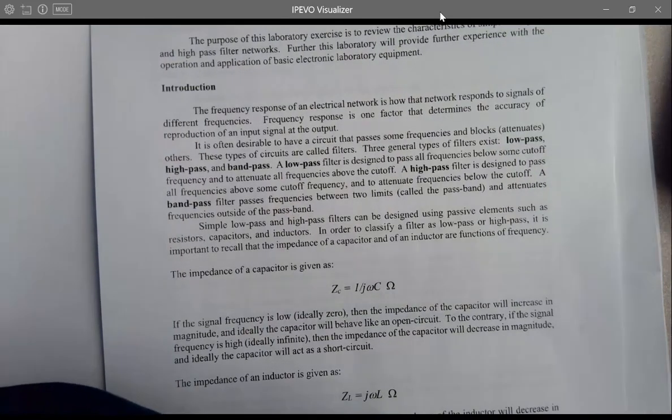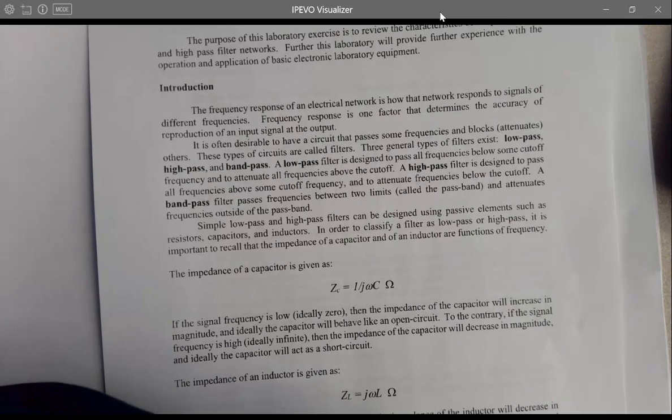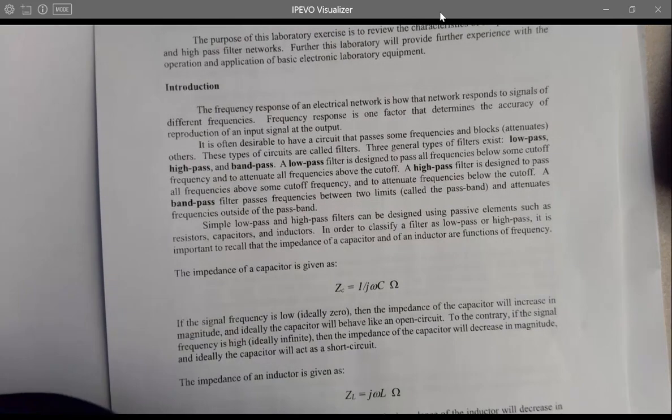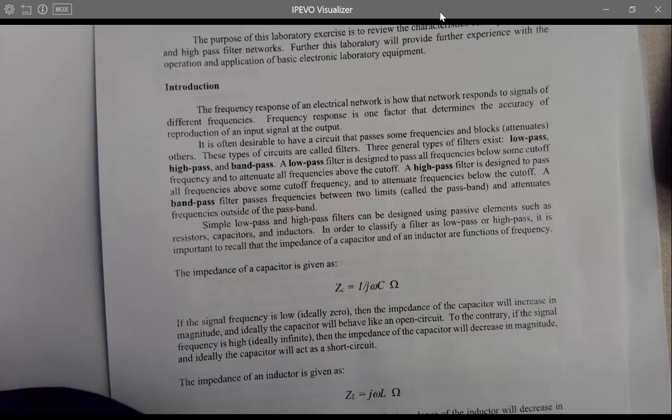Okay, so is that a high pass or low pass? High pass, because the AC signal will stay, which is the high frequency part, but the low frequency will go. What's the frequency of the DC signal? Probably, yeah, it's a very low frequency and it's being filtered out, right? So for the DC coupling, it just allows everything to pass.